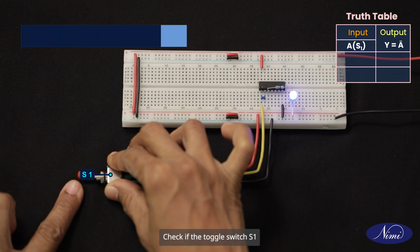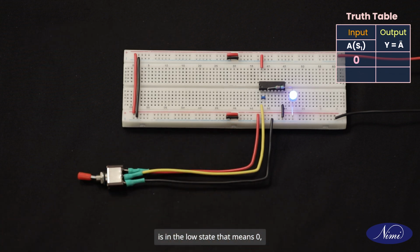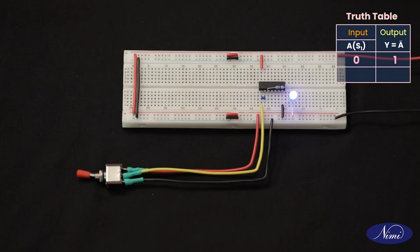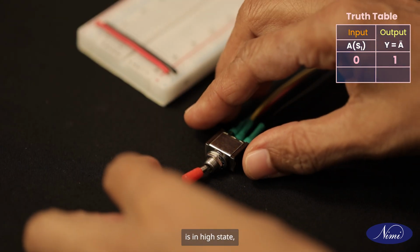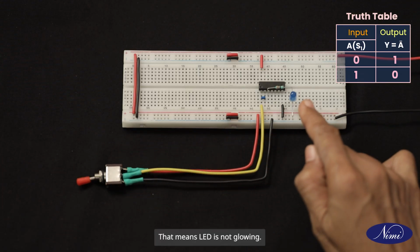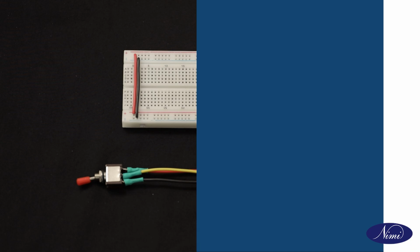Check if the toggle switch S1 is in the low state, that means 0. The output turns to 1, that means LED is glowing. If the toggle switch S1 is in the high state, that means 1. The output turns to 0, that means LED is not glowing.